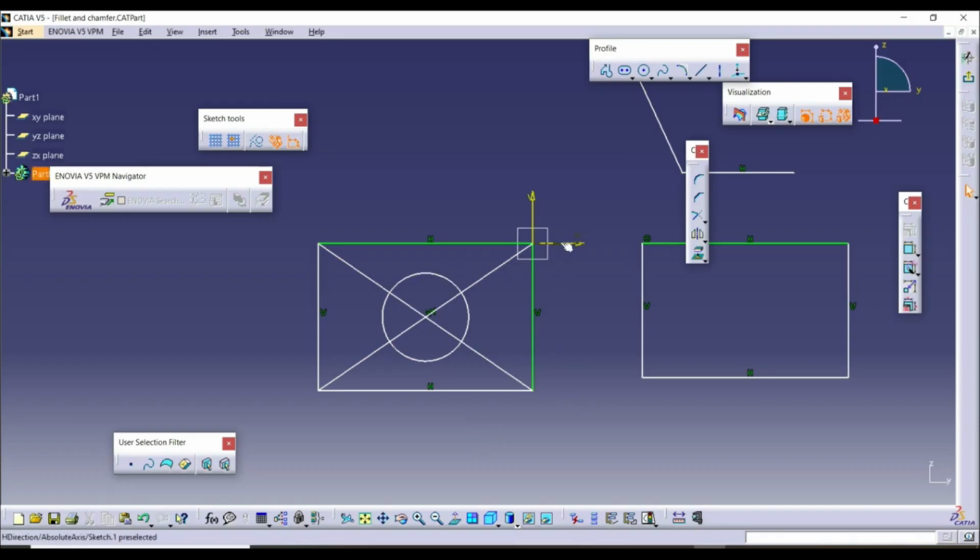But what is the problem now? For example, if you want to project this sketch to a 3D model, this is not possible, because here we have those two lines that intersect this circle. In order to make those two lines invisible for 3D projection, we can use the construction standard element tool. With this tool, we can convert standard sketch elements into construction elements. Construction elements help you to create a sketch of a desired shape and size.